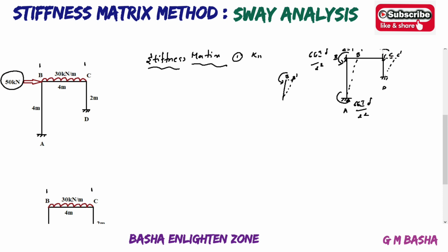So here also I will apply an anti-clockwise force. Why? Already I told you the same logic. The frame will be like this. If I apply any force, there is a chance of moving the frame in the forward direction. So like this, here also I will apply 6EI delta by L square. So your delta will be equal to 1. So directly take down 6EI by L square also. Here the same rotation will be applied like this, 6EI delta by L square. So in the continuous beam, what are we taking? So this is the continuous beam.